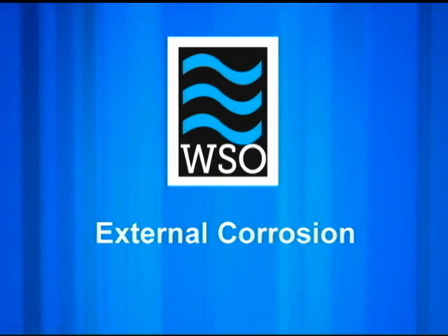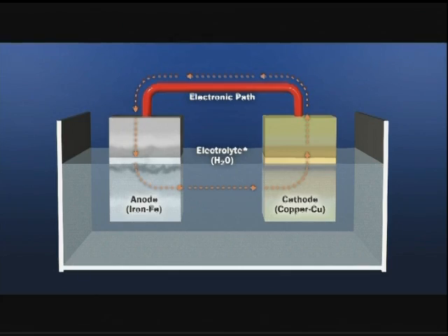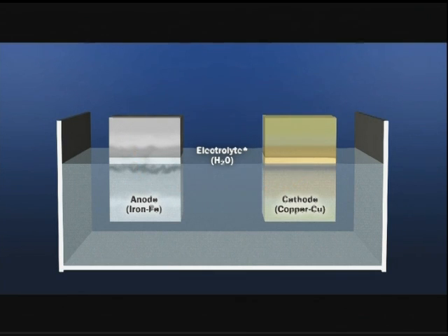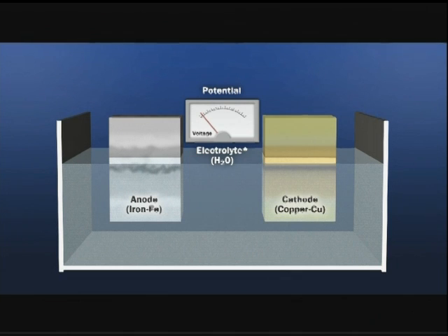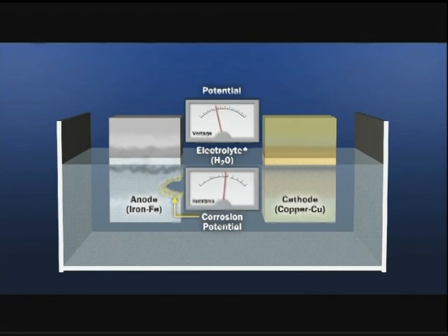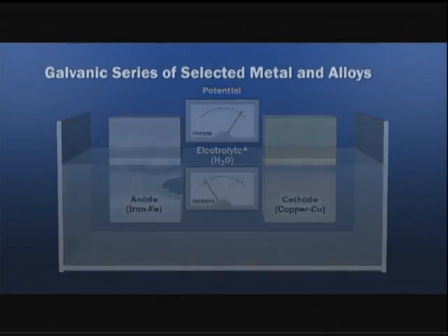By determining the conditions surrounding a corrosion cell, the theoretical rate of corrosion can be predicted. The difference between the charges in the anode and the cathode is measured as an electrical force known as potential or voltage. The rate of corrosion varies according to the voltage, electrical properties of the metals, and electrical resistance of the electrolyte. High voltage and low resistance will equal a higher rate of corrosion.